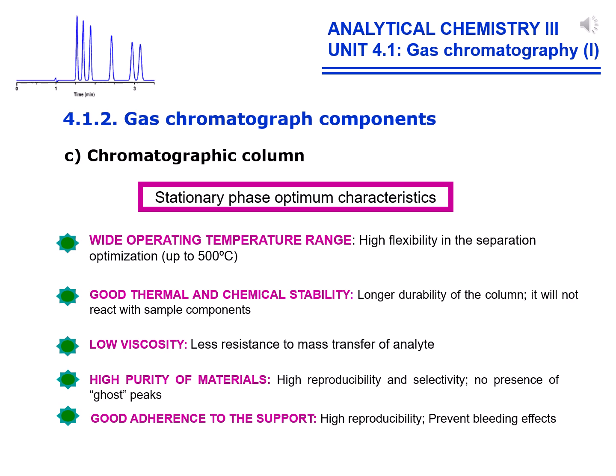The column is the core of the gas chromatograph. Keep in mind that the column, where the stationary phase is contained, is the real element of sample components separation. Thus, a bad choice of the column or inadequate working conditions according to column specifications will never allow good results. These reasons account for the vast majority of problems encountered when performing a gas chromatographic analysis.